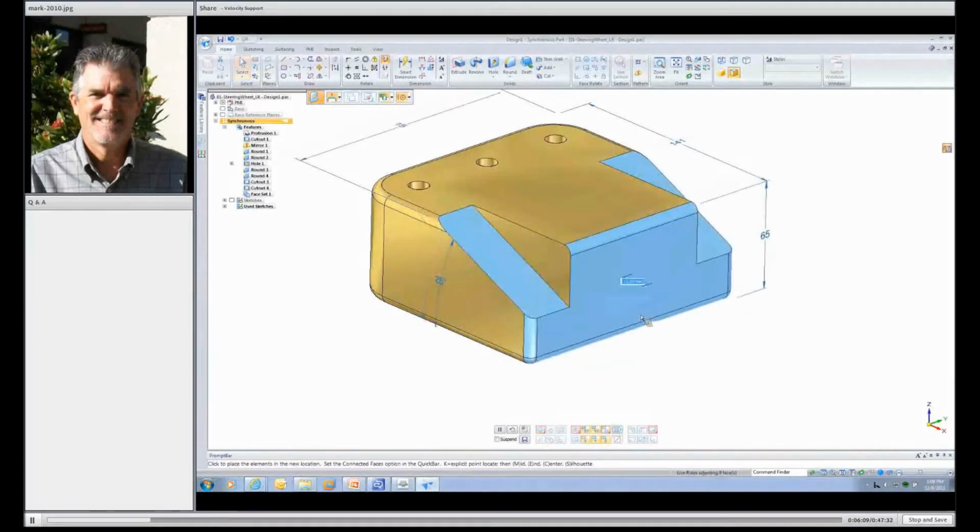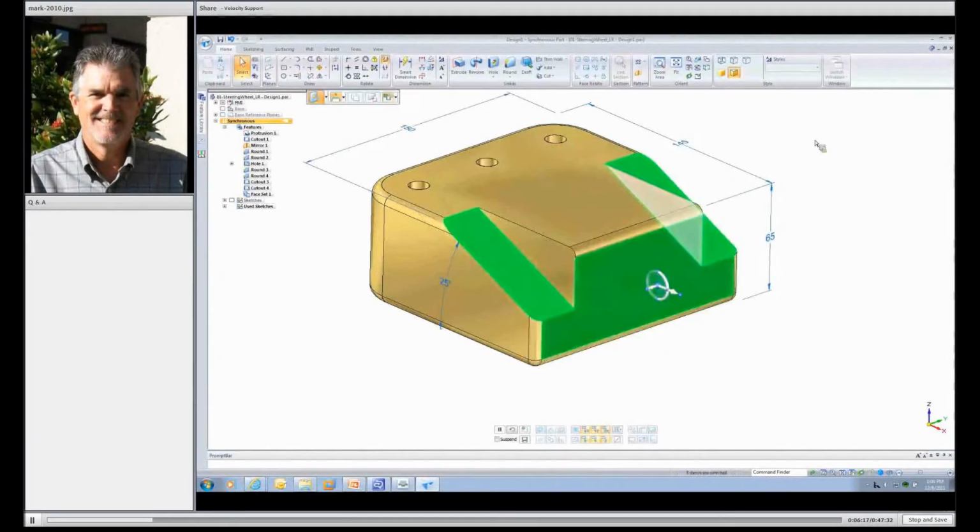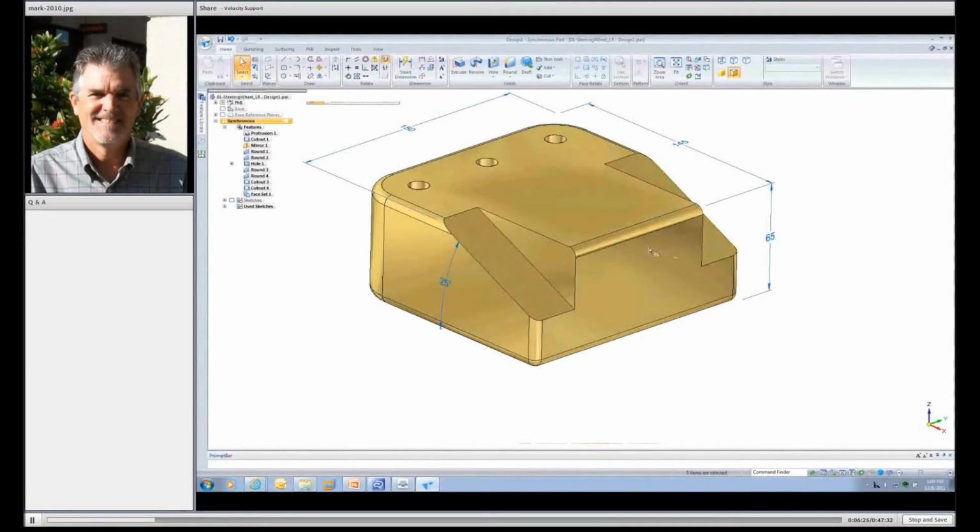Another thing that we can do is if we identify, for example, one of these angled faces. I'm going to select this angled face, and I'm going to hit the space bar, which puts me in the plus minus mode, and also identify the angled face on the right side of the model. You'll notice that when the steering wheel is touched or changed at all, it displays the full contents of the steering wheel. And the steering wheel is basically used to manipulate the faces that you select.